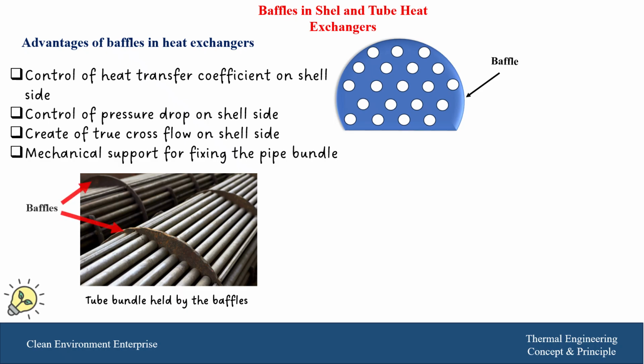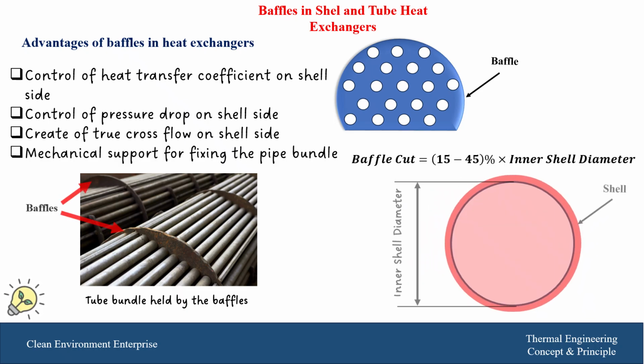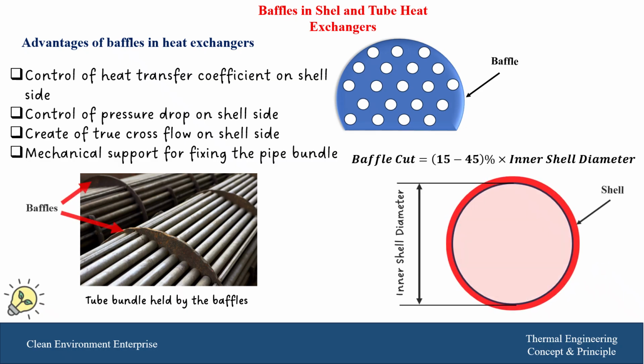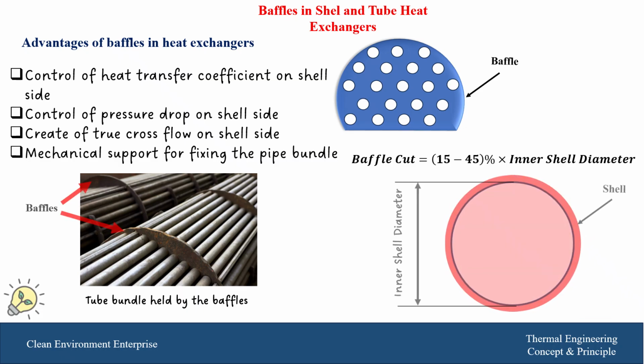heat exchanger. And usually these baffles have a cut, and it is stated by the TEMA standard to range between 15 to 45% of the inner shell diameter. And then I will explain what the TEMA standard is in the next slide.